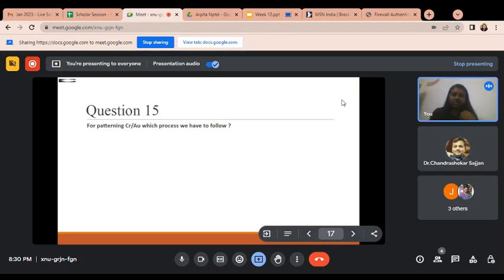When positive photoresist is used, the exposed portion becomes weaker or harder? The exposed portion will be harder actually, no, weaker. Positive will actually become weaker. Now if a mask is present, there is a chrome pattern on the mask, and below there is a substrate where the positive or negative photoresist is coated.